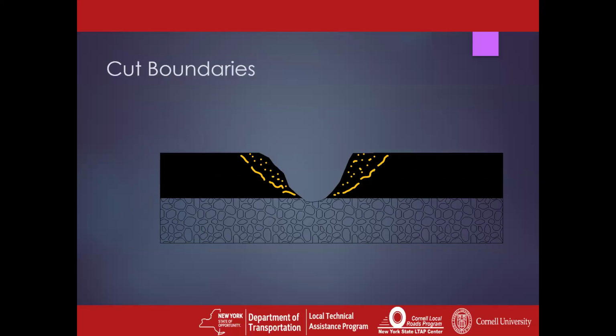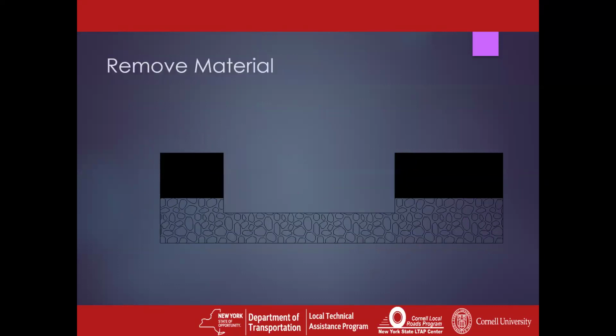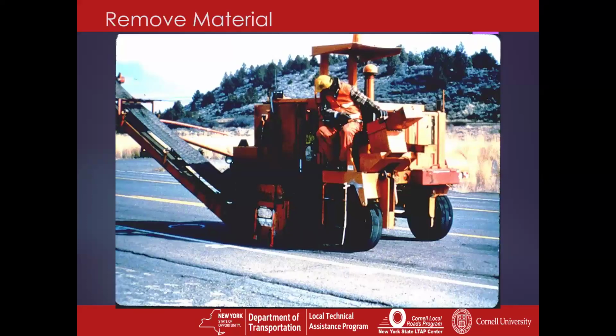And the reason you do that is you've got that deterioration that's well back underneath the surface from the edge of the hole, you don't see it. So you want to get outside of that hole, cut your boundary, go deeper if you've got problems in your granular material. Replace your granular material with good, well-draining granular material.